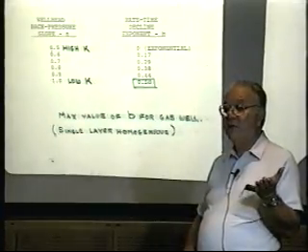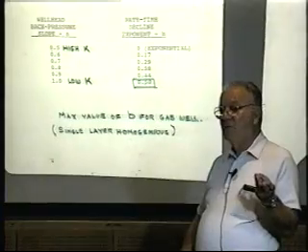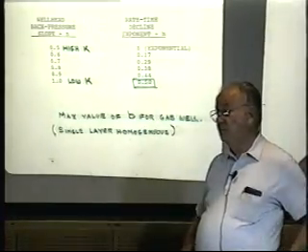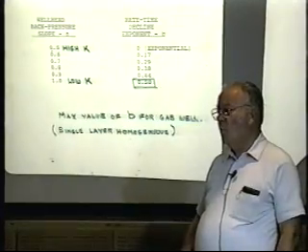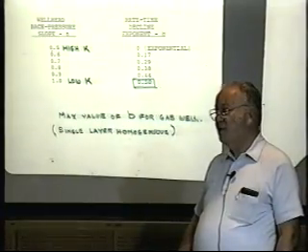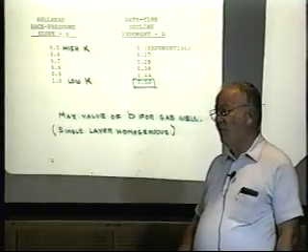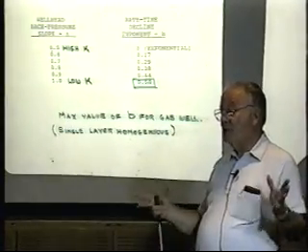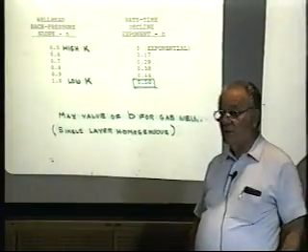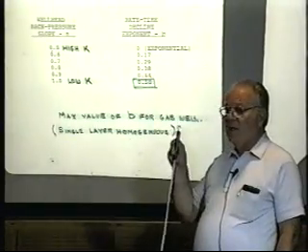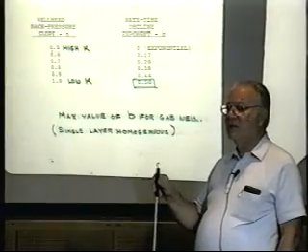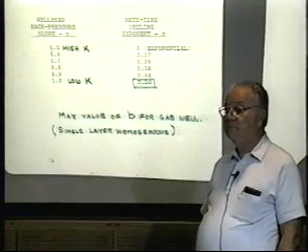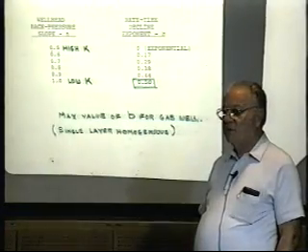Practically the whole Panhandle area, the West Panhandle field, and now also Texas Hugoton, is on vacuum. And it's been producing since about 1925. There's a couple of factors involved. Long producing time, that's what you end up with when you get into layered no crossflow. If you have a field that has a long producing time, you have a layered no crossflow system. That applies to oil and to gas.